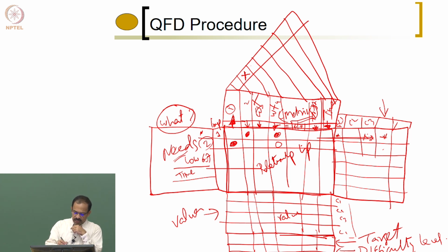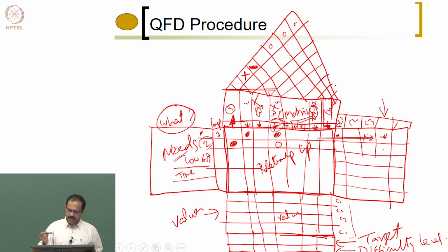But the other way, if I increase this and the weight increases, then I have a negative relationship, because I want to reduce the weight, but when I am increasing this, the weight increases, then I say there is a negative relationship. Not every pair should have a relationship. When there is no relationship, you can put it as a 0 also, or you can give it blank. Same way, I can identify for each metric how it is affecting the other metrics in the whole system. So, this is the correlation matrix.